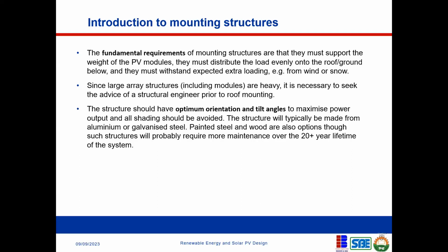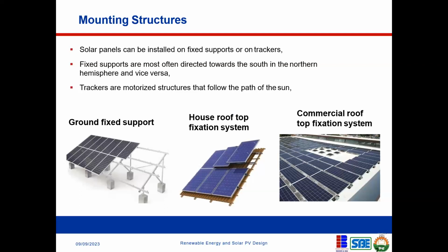Besides that, look at the building structure, making sure that the weight of the panel can be evenly distributed on the building or on the structure that you have, and that the weight is also properly transmitted to the ground, so that even in the case of wind or other extra weight that may come upon the building or the panels, it will not lead to structural defects of the panels or the structures. So it's very, very important to look at that. So have different mounting structures.